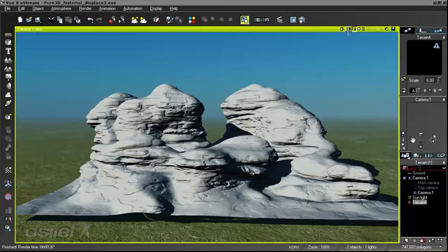So this is with those reduced settings. I also want to note that the higher the geometry becomes within the sculpted amount for the displacement of the terrain, the more roughness and finer settings we can use within the fractal for the displacement without destroying any of the geometry too much. So we could either keep the terrain like this. Of course, there are issues with the shadows